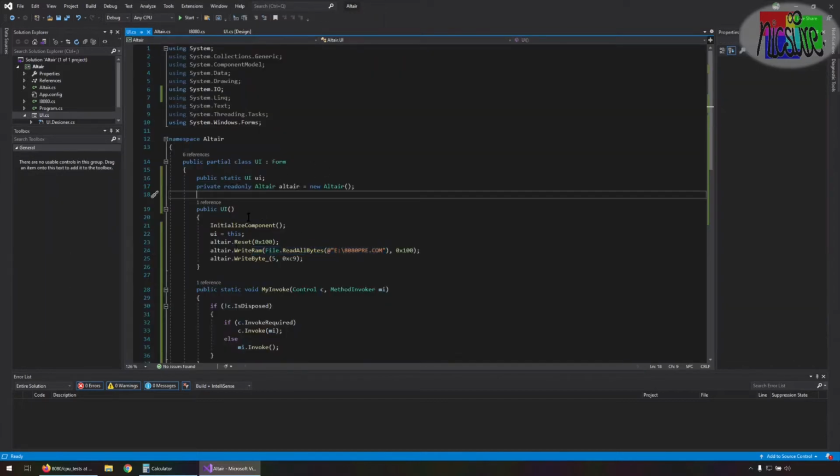We'll load it using the bootloader that you can get on the Altair clone site, and then stream the code from the serial port through the bootloader into the memory and let it run. So it's basically going to act as though it's being loaded from a serial device, like a teletype or something like that. And we'll see if we can get Basic to run.